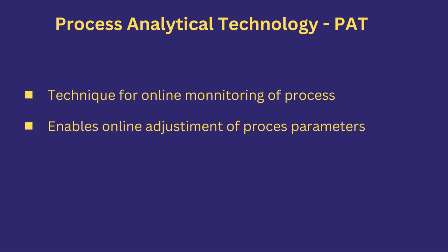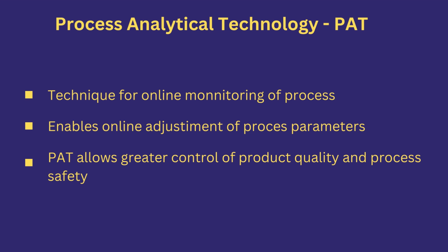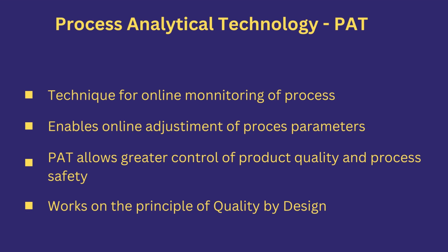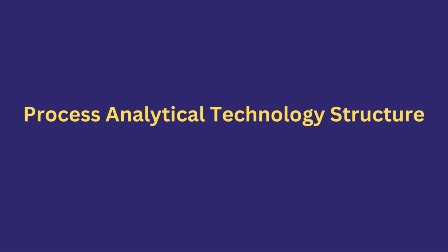PAT allows online adjustment of process parameters as the process advances through its different stages of manufacturing. PAT allows greater control of product quality and process safety, which would become difficult with the traditional stop and test method. PAT works on the principle of quality by design, where quality is ensured in the product during its manufacturing stage.